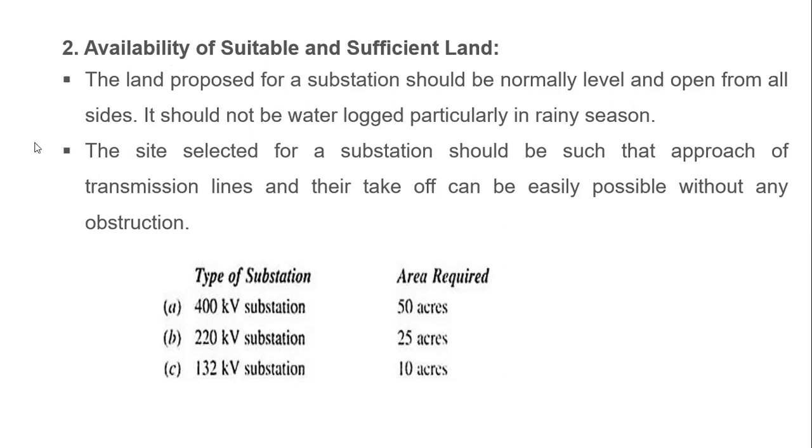That land will be open on all sides. It should not be waterlogged, particularly in the rainy seasons. First of all, we observe whether water will be stopped at that land or area, because then the substation's various equipment could be damaged quickly. That's why it should not be waterlogged, particularly in the rainy seasons.